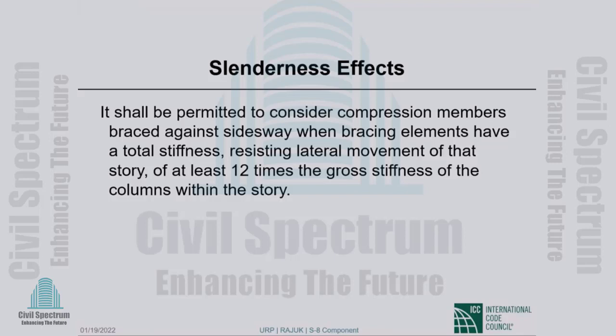So let us say you have to know the direction of analysis first of all. Okay. So when you design a column, there is an implied direction of analysis. The bending moments that are being applied to the column assume the building moving from left to right.